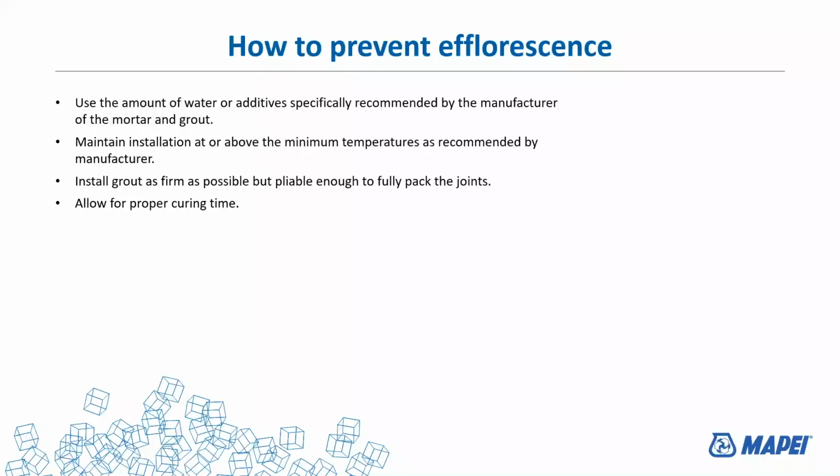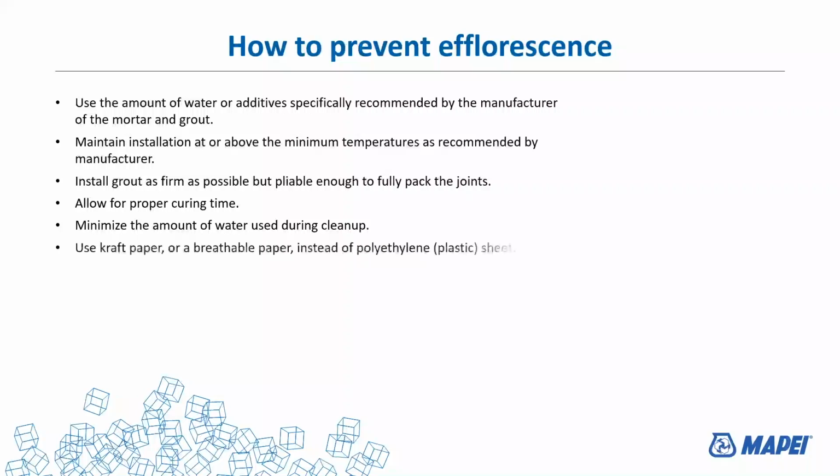Use the minimal amount of water, wring that sponge out, wipe it across, flip the sponge, do it again, wet the sponge, wring it out. Use minimal amounts of water. There's no reason to be flooding a floor with water for a cleanup. Craft paper or breathable paper is better to use instead of polyethylene plastic sheeting, because these products are breathable. Plastic holds in the moisture like we talked about, which will cause efflorescence if you're not careful.